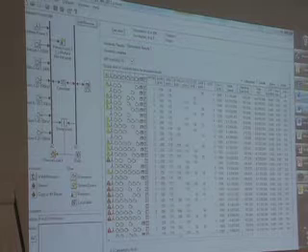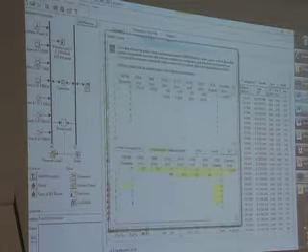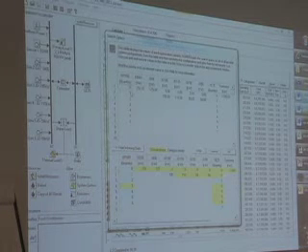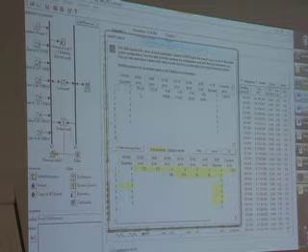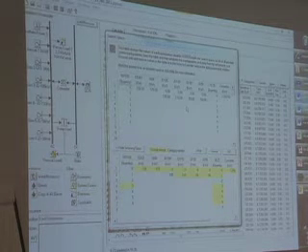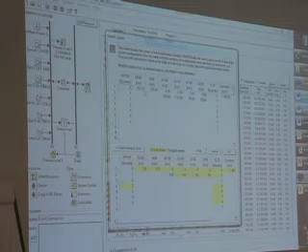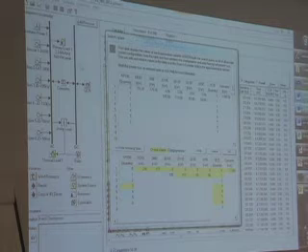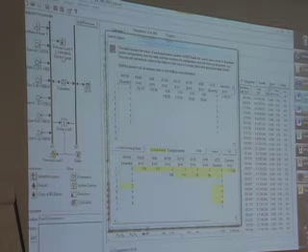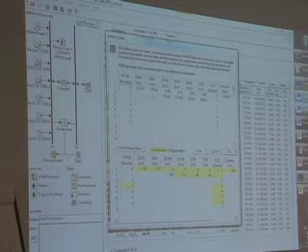And then let's look at the entire search space. Because those two are existing, we're forcing them in. We're not allowing a zero there. But then we're looking at adding, well, these are the two existing generators. This one is sized a little bit bigger than the peak load, probably not enough to cover spinning reserve. And this one is quite a bit bigger than the peak load.